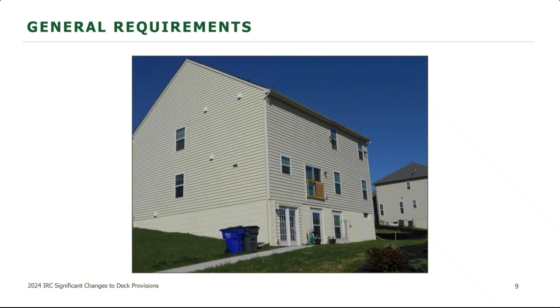They could possibly move the post or the stairs to another location so that it doesn't interfere with the door, but maybe there's another reason that it needs to actually be there. Then the existing building would have to be made compliant by possibly relocating those doors or by finding another egress path from the lower level, the walkout basement.